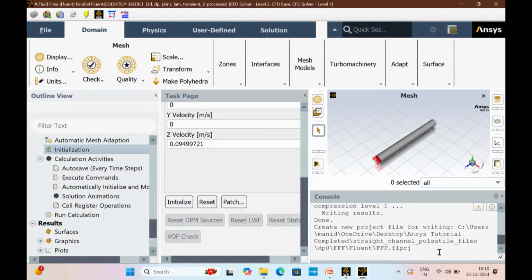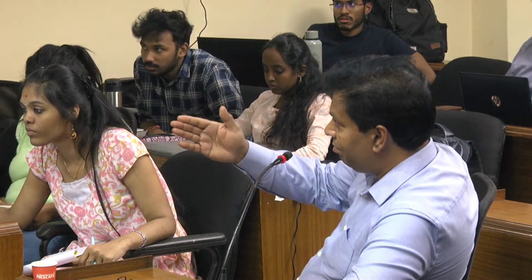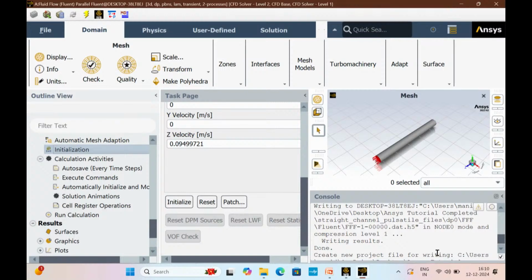No, we are not giving the parabolic. We are giving the average velocity every time. After the simulation, the flow will develop into a parabolic profile after a little distance in the developing region, but at the inlet, no, it is not parabolic. It is not parabolic because giving a parabolic profile every time is very tough. That's why he is averaging and putting a rectangular, constant profile, a uniform velocity at every point.